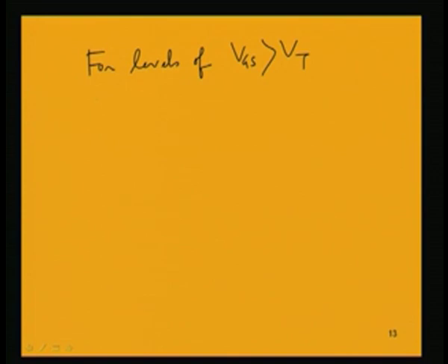So, what will be that relation? That is given by the drain to source current ID is equal to K into (VGS minus VT) squared. So, basically this is a non-linear relationship as a square is there.